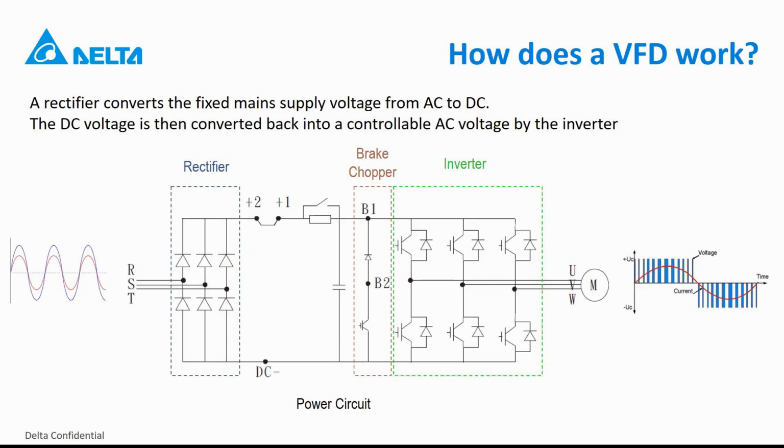Regardless of whether the input of the drive is three-phase or single-phase, it still gets converted to DC, plus and minus, and the output is always three-phase. One question we get often: can we control single-phase motors? And the answer is no. The output is always three-phase, so you cannot use it with single-phase motors.